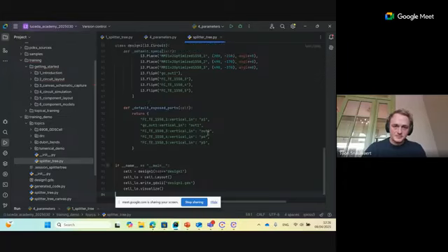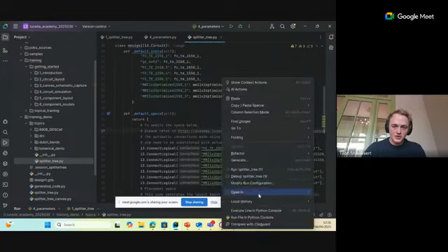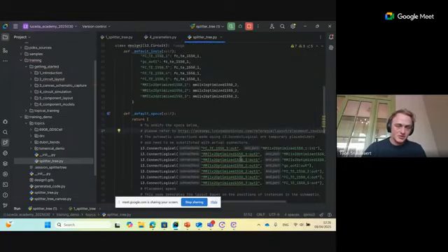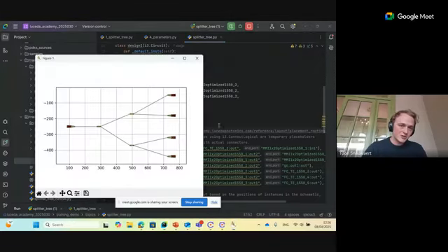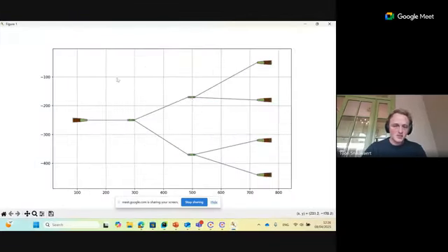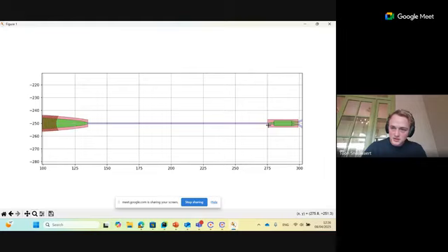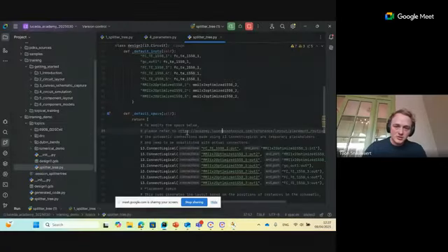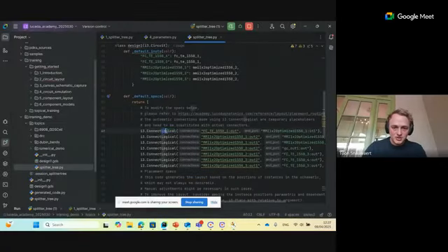And paste. And now we can directly run it. And then we will see the splitter tree that we've created in Canvas. But there's something strange going on. We can see that the waveguides are not waveguides, but they are these purple lines. And that is because in this template, we used Connect Logical, which only creates logical connections between your components.